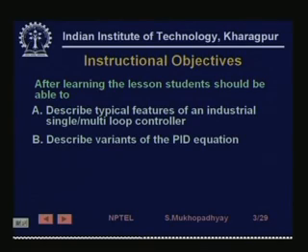There are various variants of the PID equation. If you read the PID equation, sometimes you feel that is the only variant and you might implicitly assume the same variant to be existing in your controller. That is not the case. The several manufacturers implement PID controllers in various ways and you need to understand that before setting gains.